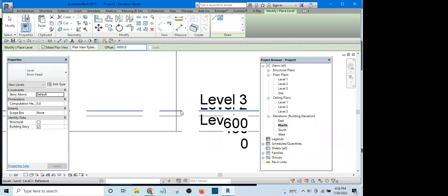This is for your first floor slab, and change it back to 3,600 and pick this one, and this one is for your first floor headroom, and change it back to 150 and pick this. This is for your second floor slab. That is if you have a second floor. And that is how you can be going like that